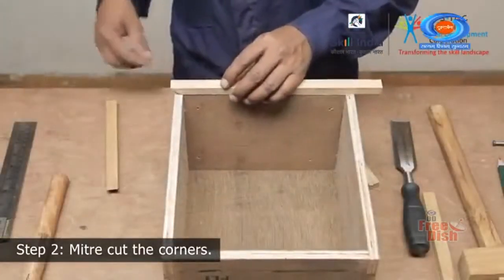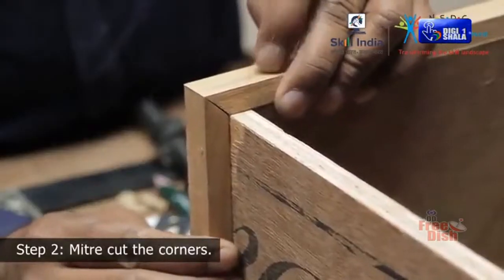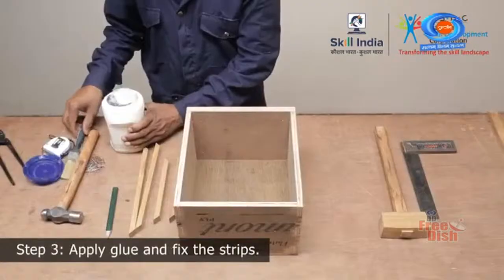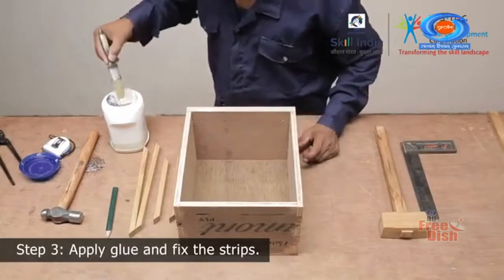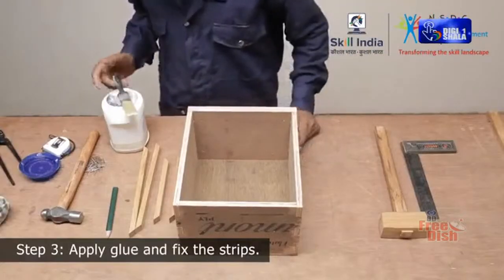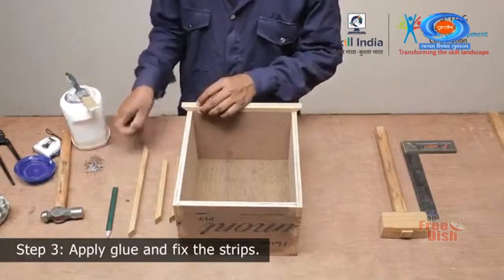Dry fit the two pieces to check the accuracy. Once satisfied, apply glue on the inner side of the strip and place them on the face side edge of the drawer and align them properly to its edge. Press them and drive in some wire nails to strengthen it.